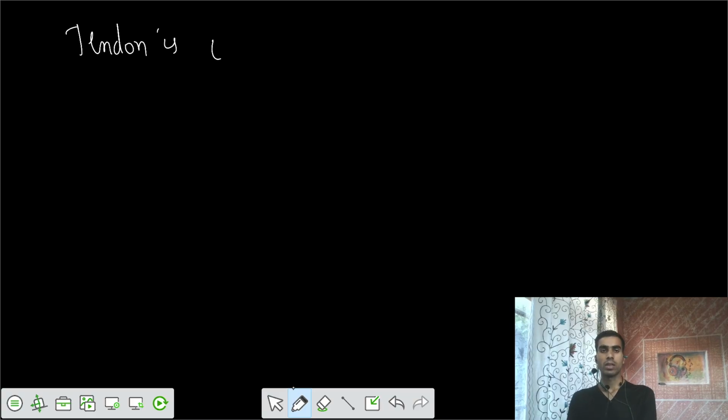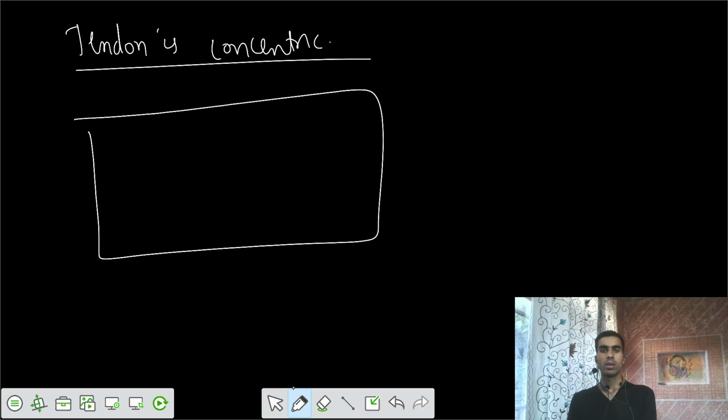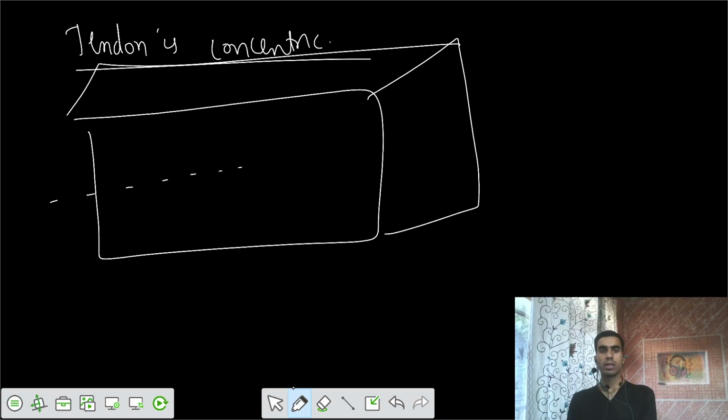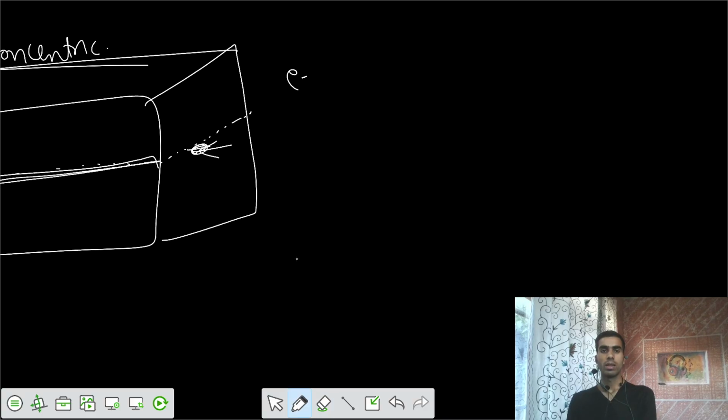That means along the neutral axis of that beam, let's say this is your beam, and this is our neutral axis along the length, and along the section the neutral axis is in this way. Your tendon has been placed along the same line, and you're applying that P force along that same line. That means e is 0.